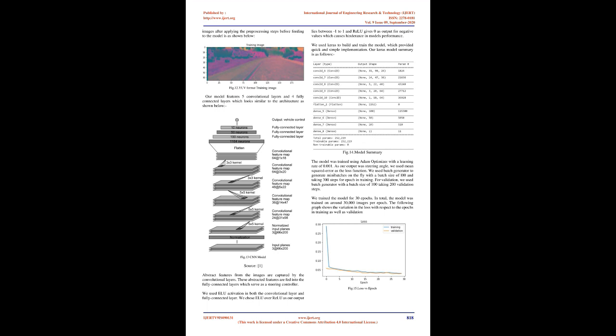The second image shows the flipped representation of the original first image. When the image is flipped, the corresponding steering angle is reversed. The fourth image is the combination of image flipping, image panning, and brightness alteration applied on the third image. These data augmenting techniques help make the model more robust in predicting the output even after slight changes in the input images. As a result, the model more precisely learns the mapping of input images to its corresponding steering angle.